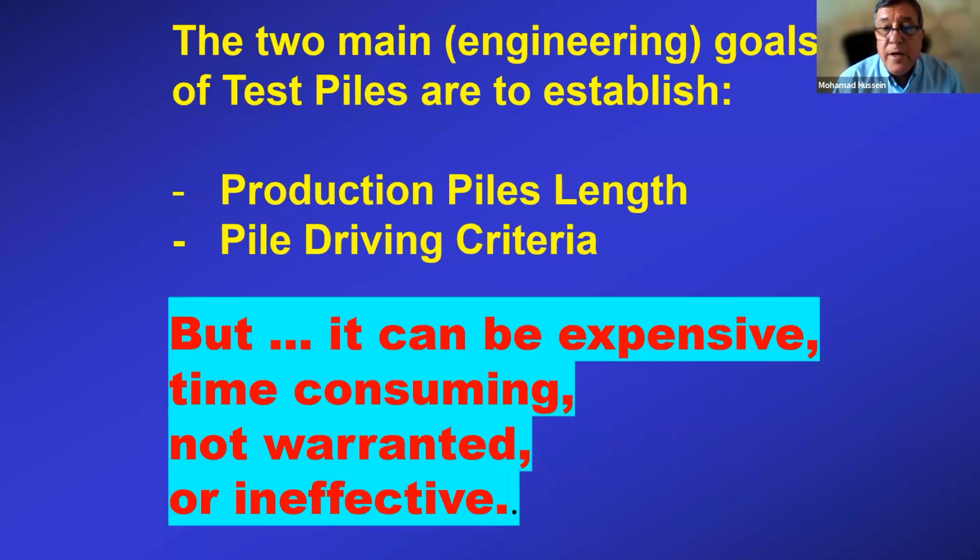It is time consuming because you have to do a test pile program, and then you have to come up with production pile length. You have to make the piles, bring them, and so on. So time consuming. It might not even be warranted in certain cases, and in others it could be completely ineffective.